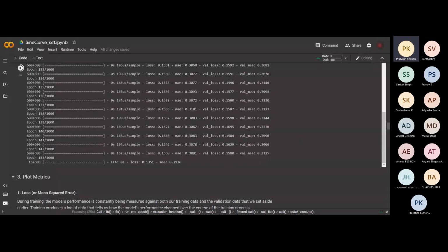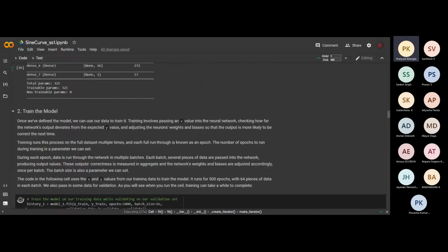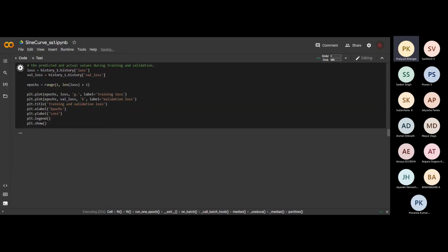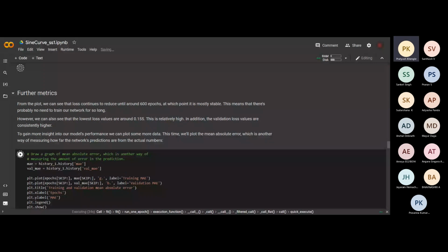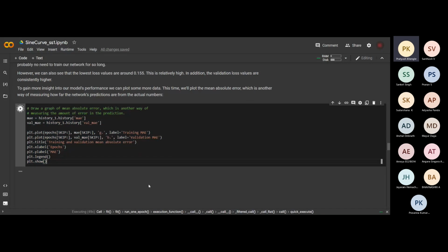I hope you guys were able to follow. We just first added one additional layer, which increased the accuracy of the graph, and then we converted it to a TensorFlow Lite model because we can't upload it as a TensorFlow model, and we converted it both in a quantized manner and an unquantized manner. We have to quantize because we don't have that much space on microcontrollers.